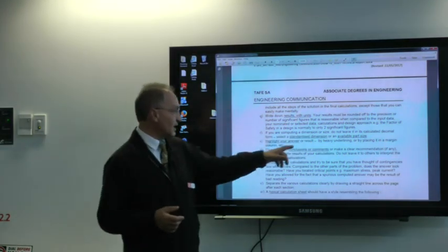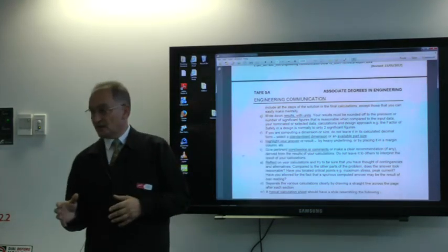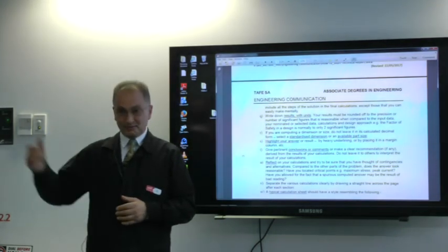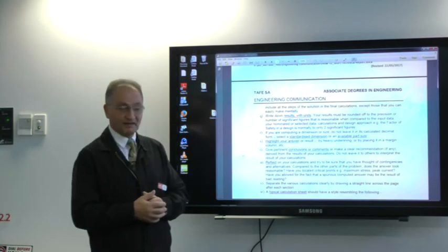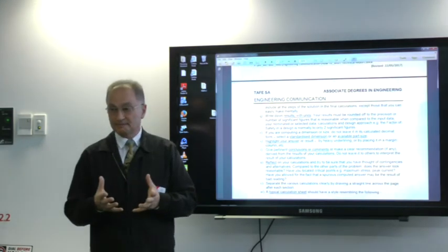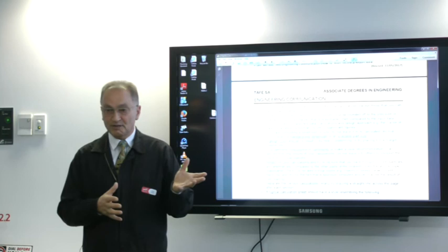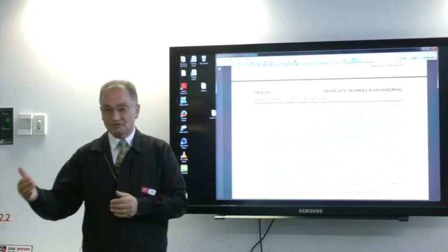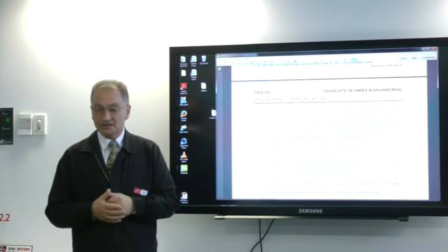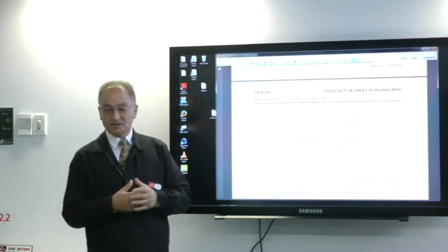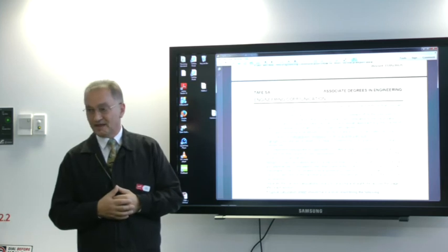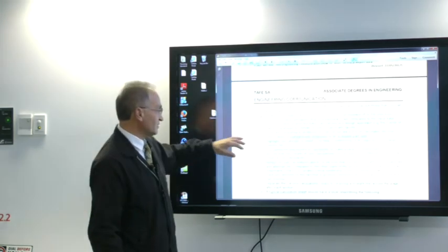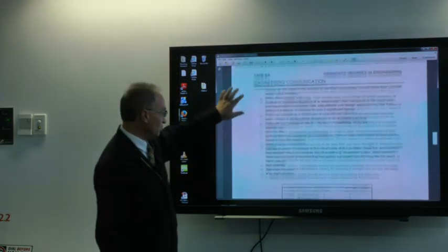Standardised dimensions and parts. You might be designing this air conditioning plant that I keep talking about for the upgrade in one of the rooms. You may have come up with a design of a certain compressor, but the standard ones available from retail are only, you know, in multiples of 10 kilowatt, let's say. So you need at the end to come up with a design that you can actually purchase, not one that you can't get on the market. So standardised dimensions, standardised parts are very important.